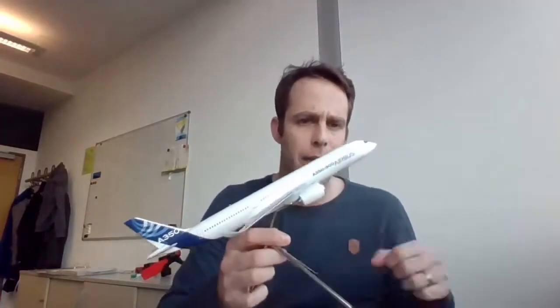However, it's not that dramatic because what you usually have is that your input is slow, right? And your noise is usually pretty fast. Think of an aircraft. The pilot steers the aircraft with a stick, right? So it moves forward, it moves back. Or think of you driving the car. Let's say it's a normal car, not a race car. You drive like this, right? Or you push your gas pedal at a certain speed. This is comparably slow. When you look at sensor noise, it's pretty fast.